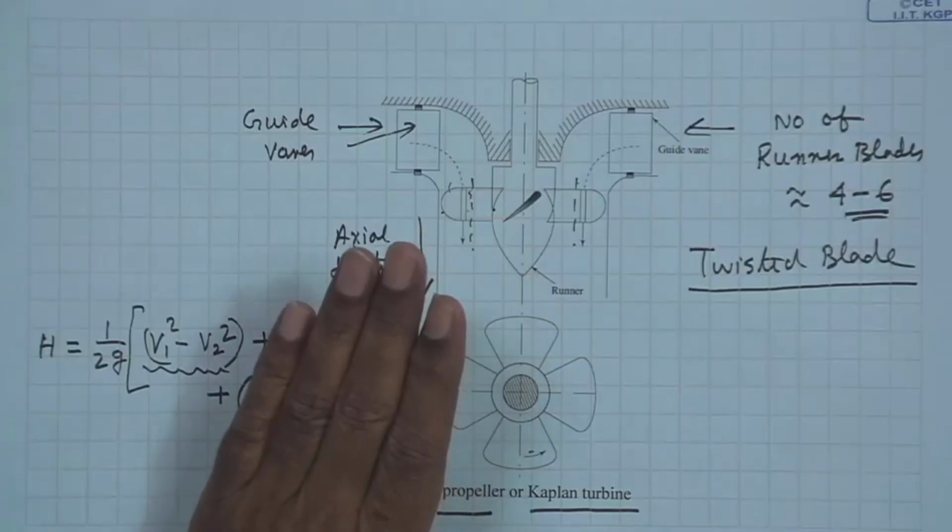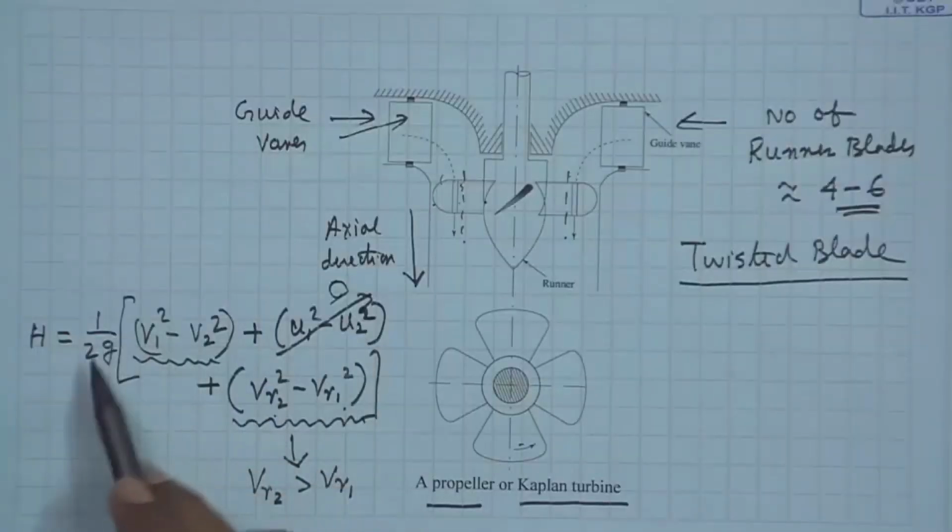There are machines which are axial flow but impulse, but for axial reaction, the axial flow turbines are axial flow reaction machines, where the flow passage is a converging type, that means the cross sectional area perpendicular to the direction of the flow. In this case, it is the axial direction. There is a reduction in the area to increase the relative velocity to get a drop in the static pressure or static head of the fluid in the runner. So, this has to be also kept in mind.